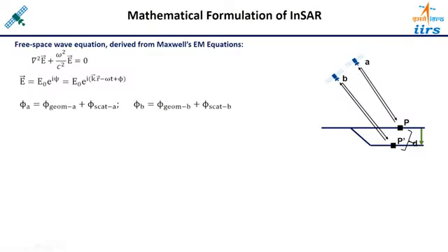Similarly, if you draw this triangle, let us say B to P prime to P, P to B. This side is known, this side is not known, but it can be calculated from the triangle A to B, B to P. A to B is known, A to P is known, so B to P we can calculate, and this particular angle is also known. So from this triangle BP can be calculated.